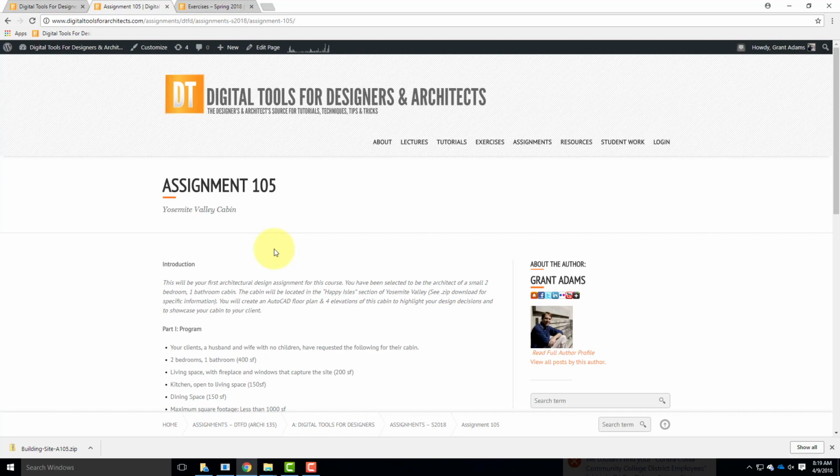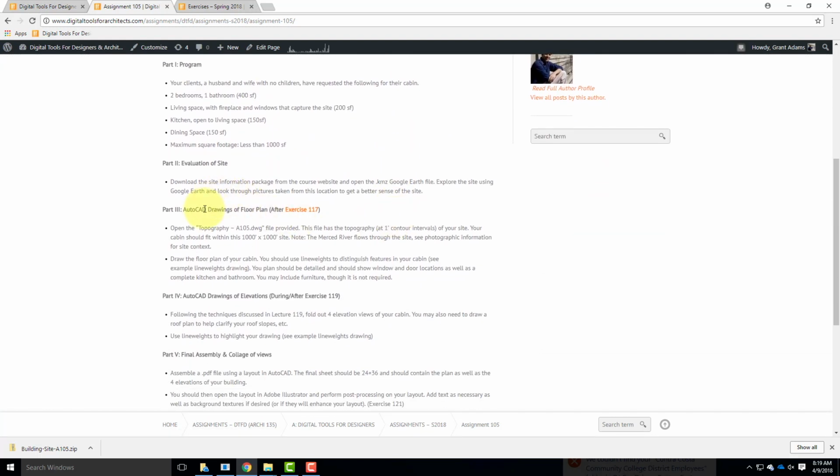We're going to start today with part 2. We're going to evaluate this site, and I'm going to show you the site, and we'll talk about it in a little bit more detail. Let me scroll down here a little bit. Next thing, part 3, you're going to start today working on this. You're going to be drawing floor plans. I have a sample file that I'll let you download that has the site topography on it, so it has the hill that you're going to be building on. The topography, by the way, is at 1 foot contour intervals, so every line represents 1 foot of elevation climb.